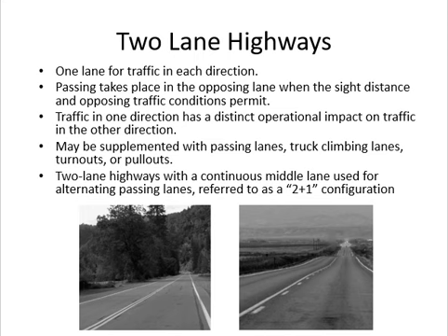On two-lane highways, sometimes we give temporary lanes. So it's two-lane. It's basically two-lane. The default is two. Okay, but we know that there can be heavy vehicles. There could be some problem at the road. Okay, so we may give a short temporary lane. Okay, and that short temporary lane can be used for passing or truck climbing.